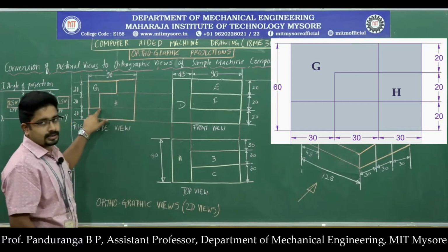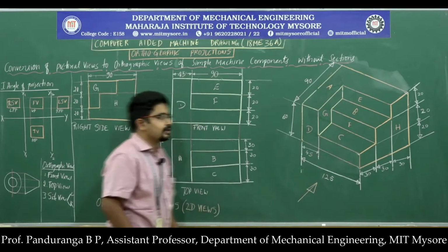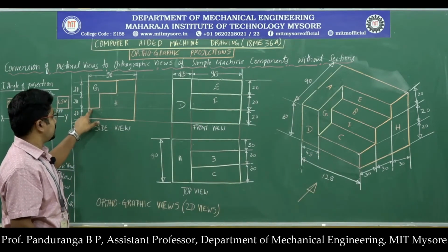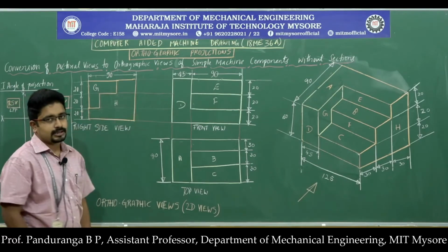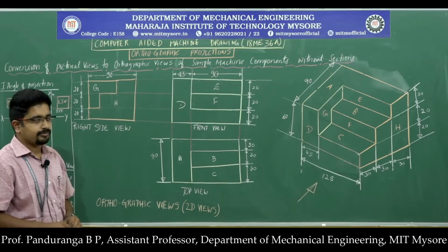At this projection line, after that I need to draw a 30 mm horizontal line. So for that, I will continue on this projection line till I meet this end. That completes the construction. Now I need to thicken all the visible edges.